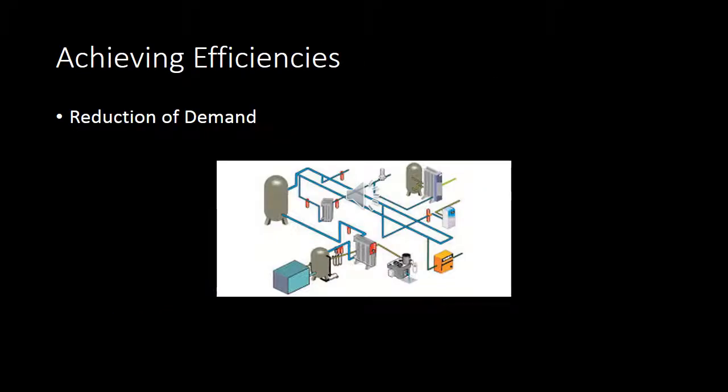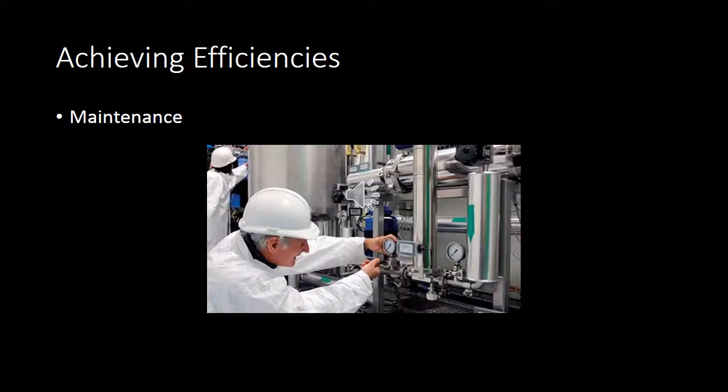There are many ways to ensure consistent, reliable, and efficient use of energy in compressed air systems. Reduction of demand. Because of the relatively expensive operating costs of compressed air systems, the minimum quantity of compressed air should be used for the shortest possible time, constantly monitored and compared against alternatives. Maintenance. Inadequate maintenance can lower compression efficiency, increase air leakage or pressure variability, and lead to increased operating temperatures, poor moisture control, and excessive contamination. Better maintenance will reduce these problems and save energy.